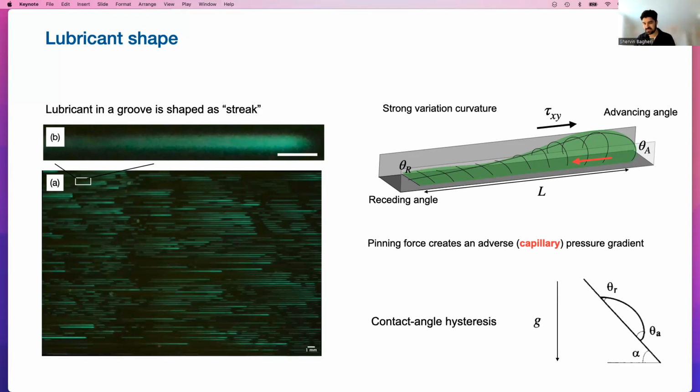This is basically the same mechanism, this contact angle hysteresis, as when there's a drop on a windshield that can remain fixed even though there's gravity, right? So there's a difference in contact angles, which creates a Laplace pressure, which can resist gravity. So instead of gravity here, we have a lubricant droplet that can resist the shear stress.